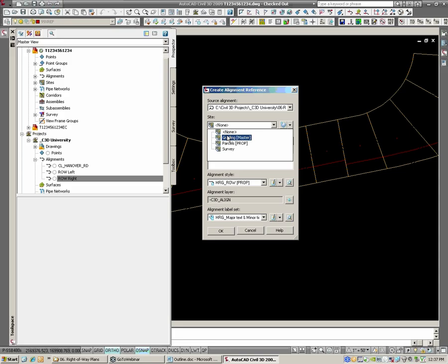And I see a lot of people doing that, and typically when you're making an alignment for anything else, always have the site set to none. You don't want to have alignments a part of a site, ever. Hardly ever. This is the one situation that I know of that we use currently where we'd want to have an alignment a part of a site.